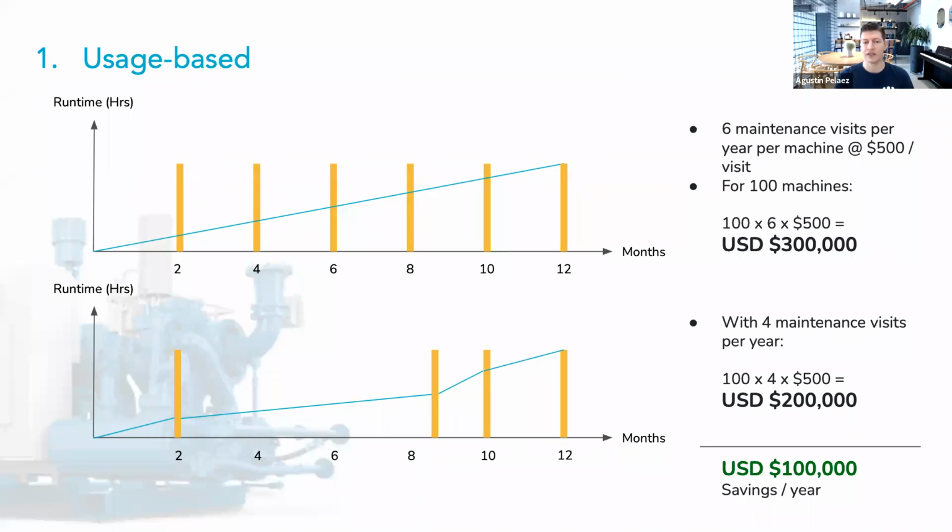And from a system point of view, it's a very simple device. Literally what you need is just one or zero, like on or off, which could be accomplished by a current sensor that is attached to the power line of the machine. If it has current, then it's a 1. If it doesn't have current, it's a 0. It could be a vibration sensor that, if it's vibrating, it's working. If not, it's offline. And that way you can start having a runtime figure or an hourly usage figure